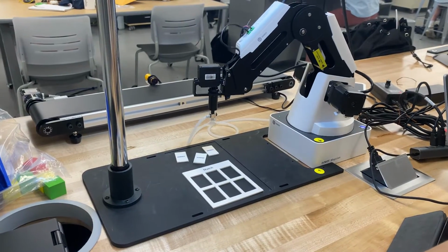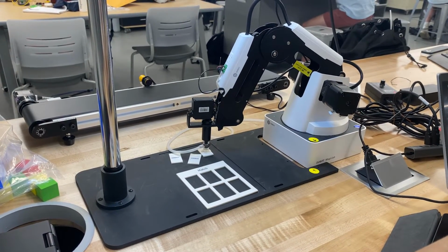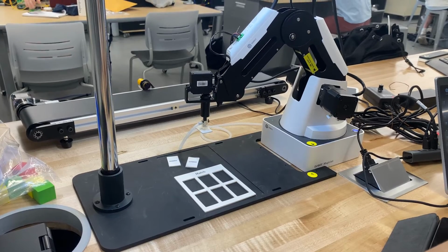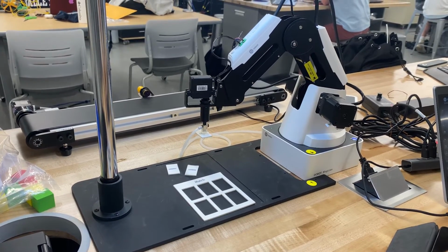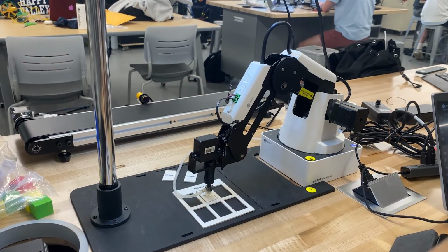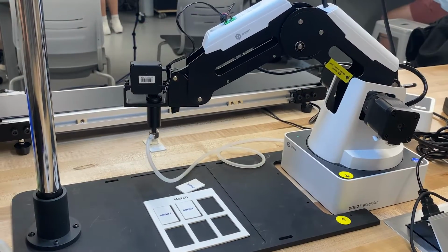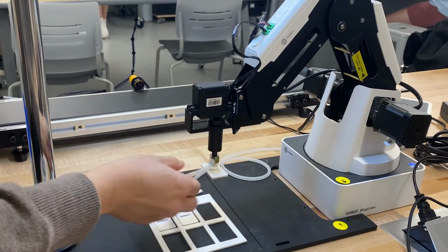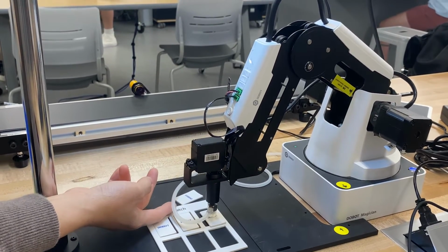Our team then explored the use of the robot's feature matching to determine the geometry of objects rather than color. Using feature matching, our team was able to determine the positioning of a rectangular block, pick up the block, and then adjust the positioning and orientation of the end effector to insert the block into an appropriate slot.